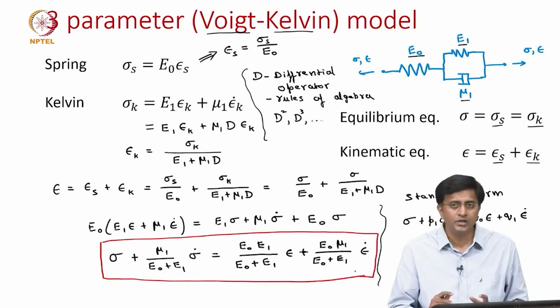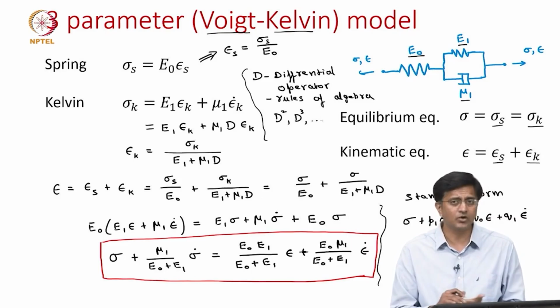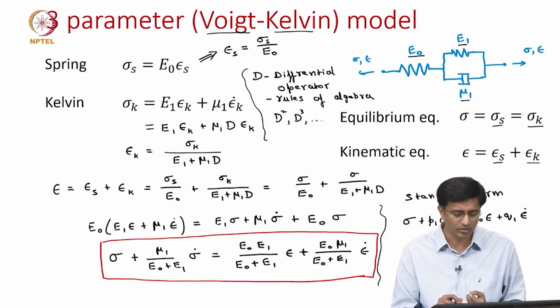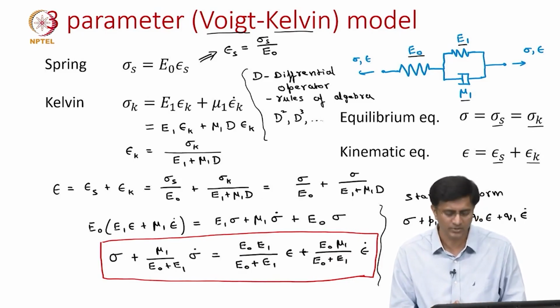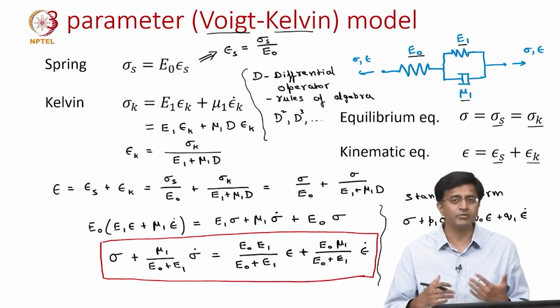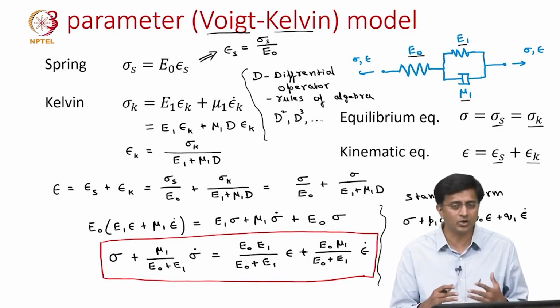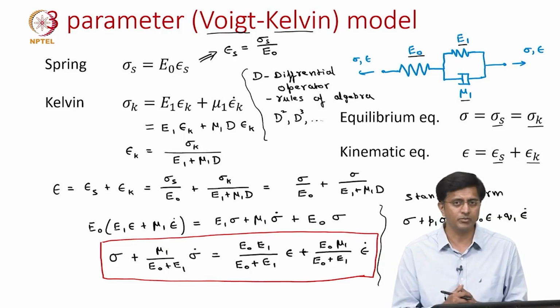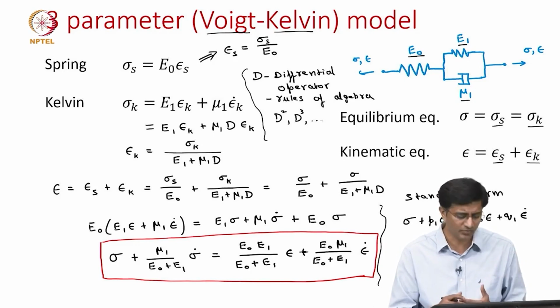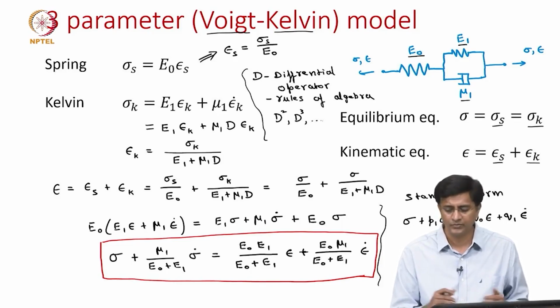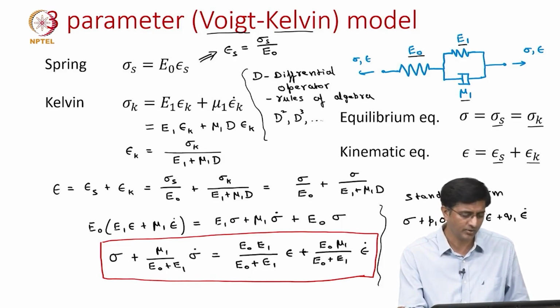As you can see, if you compare this equation with the equations we got for the Kelvin model or the Maxwell model, it is a little more elaborate, or a little more complex, meaning that later if we want to use this equation to solve for a particular load, solving will not be that easy, it will be a bit tedious. So, we should find other ways to solve this differential equation, or to find the response for a particular load. So, we will see that with creep loading.